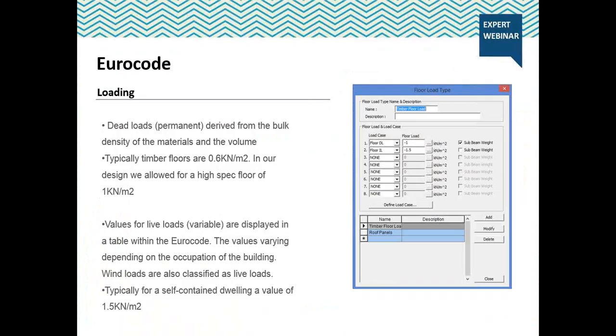In addition to this, lateral sway in the steel moment frame, for example, is limited to height divided by 300. With this in mind, within the guidance of the Eurocode, these factors used in the checks on the structure allow for a design life of 50 years for a dwelling.